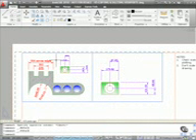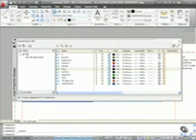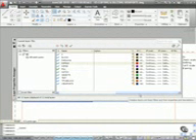So what I can do is double click here, and I can now go to my layer properties manager, and there's my dimensions 10 there. So I select in the layer properties manager here, I have to scroll across. When I come across here, you can see as I pan across, the description is empty, so I'm going to drag that and make it smaller. You've got these 2 icons here. This one here is freeze in any new viewports, but this one here is freeze in current viewport.